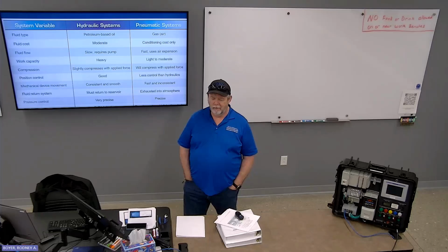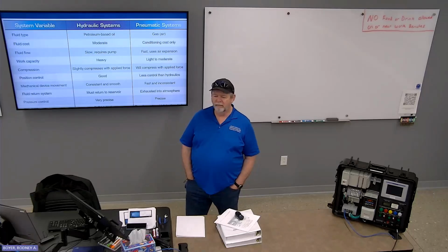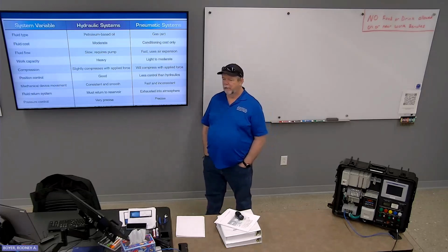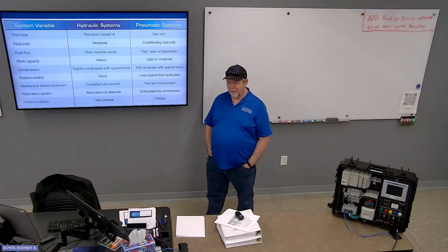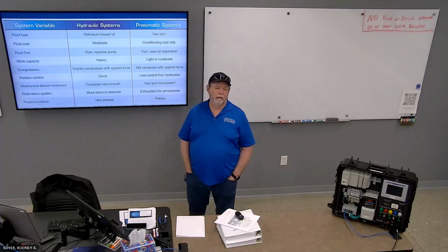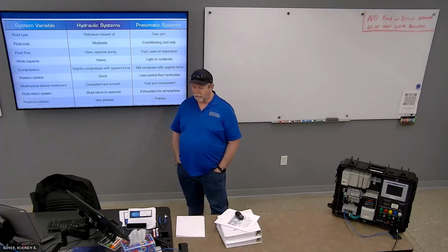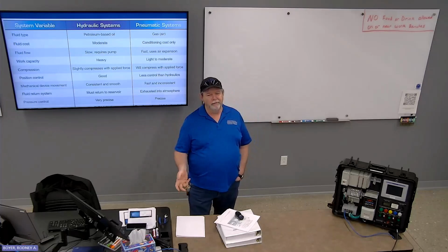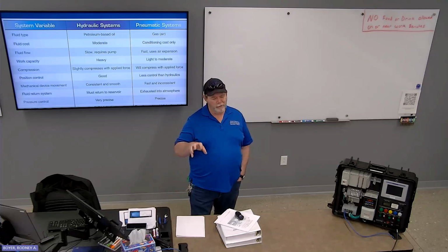So conditioning, does it have to do with the actual condition of the equipment? Condition of the fluid. Compressing the air, running an air compressor, would that fall into it? Yep. When you compress air, you're also compressing moisture that's in it. So, one, you're going to want to have preferably an automatic drain on your storage tank for your pneumatic system to let all the water out of it. But that only gets most of it.